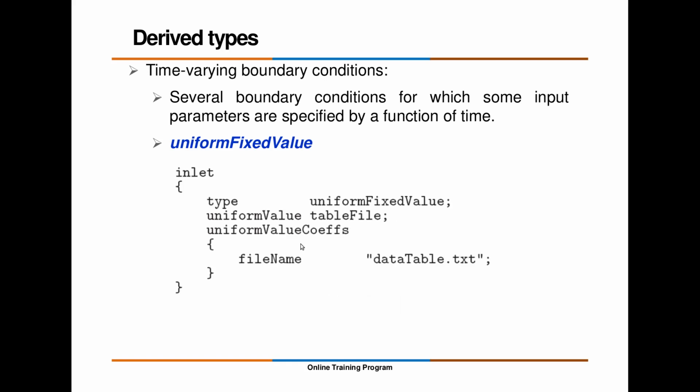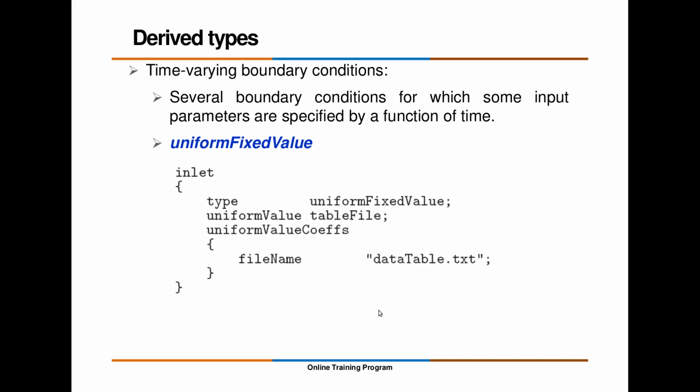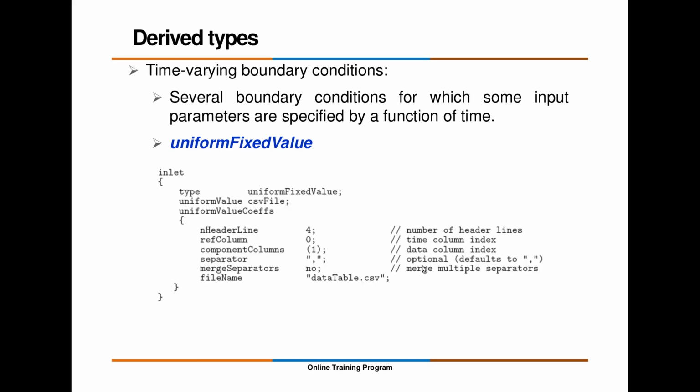Then you have the leverage to specify through some data table. You can specify a text file, so if you do not want to write it this way, then create certain text files. Let's say from 0 to 1 second we have one value, from 1 to 2 another, and 3 to 4 another. Either you write it down here itself or go with this type of data table. Either way you can specify.